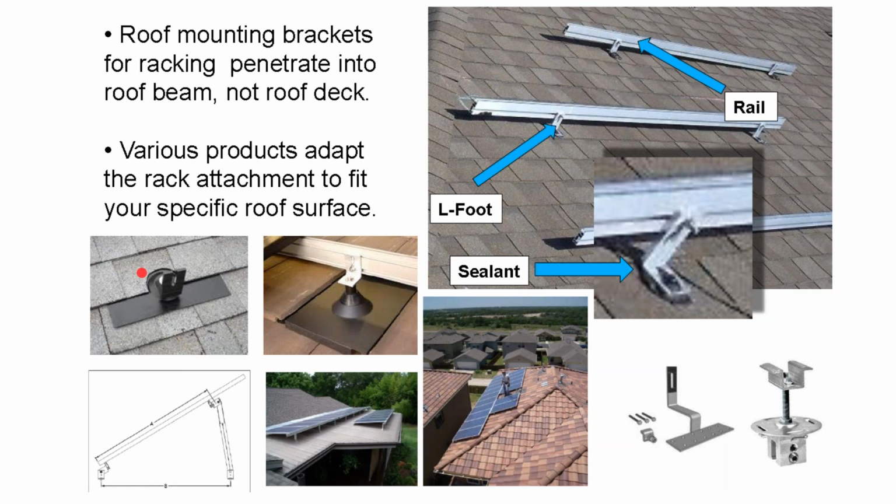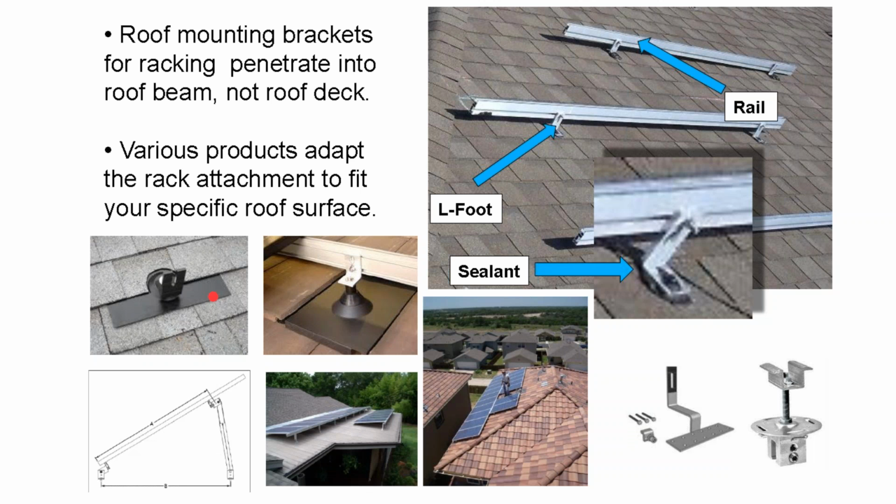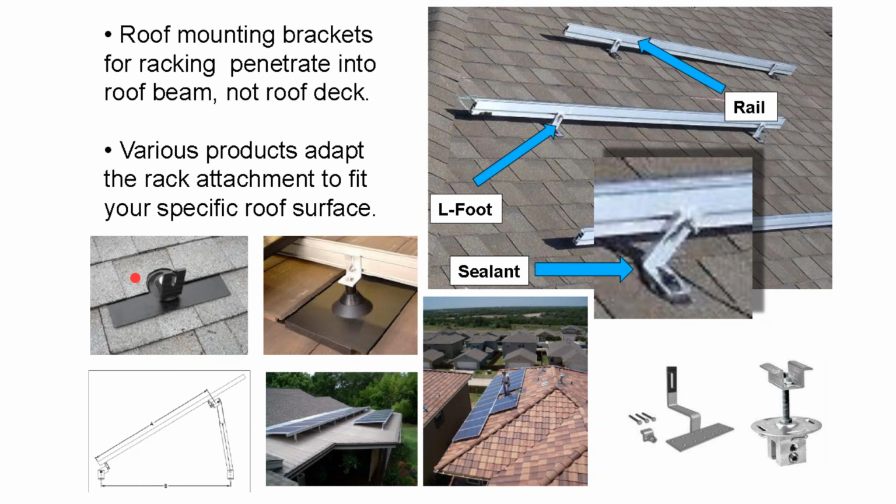Now, it is not a perfect process. If you are doing new construction with shingles, get the solar installer out there to put these flashings in as they're shingling the roof, because otherwise you got to get up underneath the shingle with a pry bar and pry out roofing nails. And particularly if the roofer is trying to do a good quality job and puts in a bunch of roofing nails rather than standard, it becomes a nightmare for the solar installer.